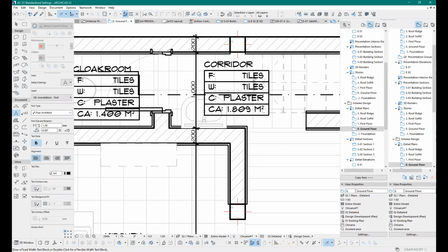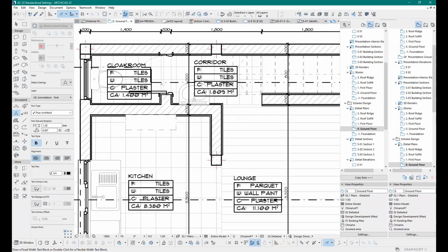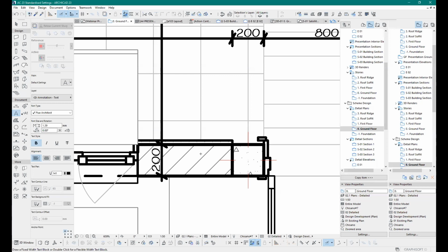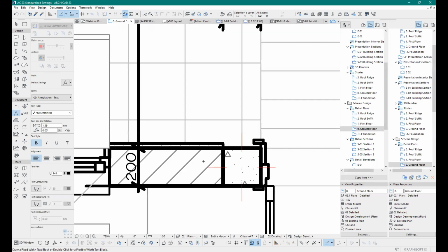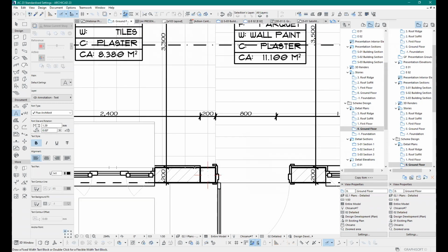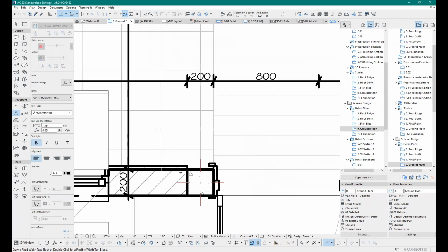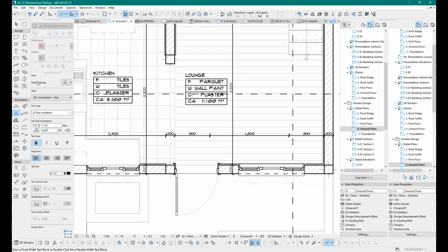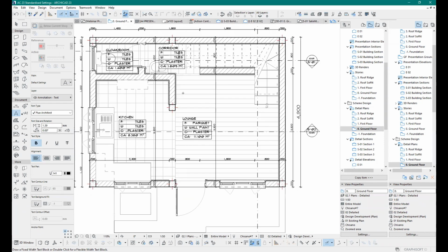This is a flush fixing, or I may decide to show a different kind. And when detailing this, you will need to show all the layers of the wall so that you may be able to define accurately the clearances for that door. So you need to make sure that your building materials are done well.